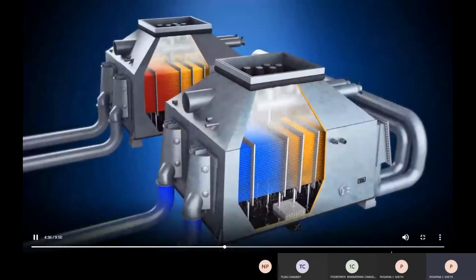Plant Miller uses a closed-loop circulating water system that allows water to be reused over and over. One way we use water is in the condenser, where steam enters from the turbine and condenses back into water as it passes over tubes filled with cool circulating water, which is chlorinated river water from nearby Mulberry Fork of the Warrior River. The condensed water moves into the hot well, where it re-enters the system to be reheated, turned back into steam, and continue its use throughout the plant.